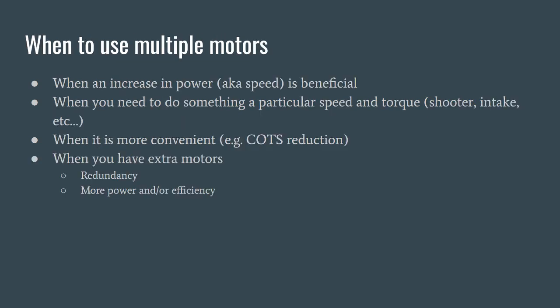So sometimes it's tricky to figure out how many motors you should use. Generally, you just up the motors if 20% stall torque is not working out for how fast you want the mechanism to be. It's pretty simple. So we'll go over each subsystem and what general goals I would have for the subsystem.